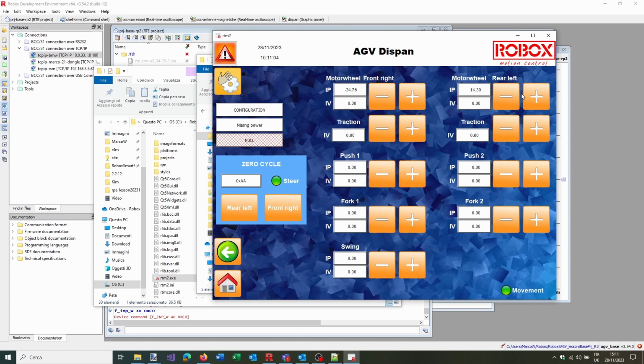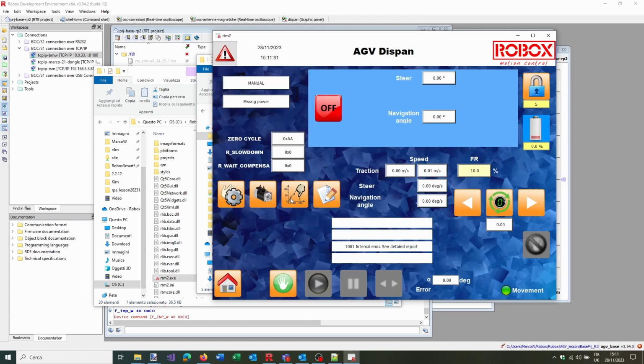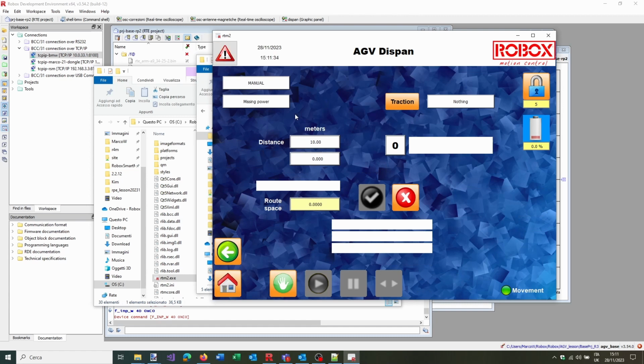You can check that your steers move left and right in the correct way. You can check the position of the zero reference of your steers, and that moving your traction wheels, you will make the correct distance. Keep in mind that traction wheels have the same revolution, which is only 1. Since now in the configuration you just move axes one by one, you have not yet done this 10 meters calibration, because this will be done later while you put the AGV on the ground.